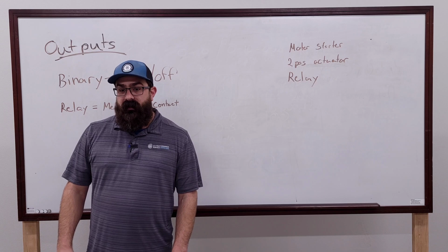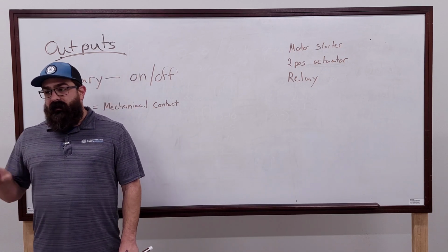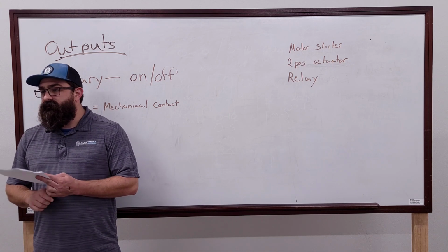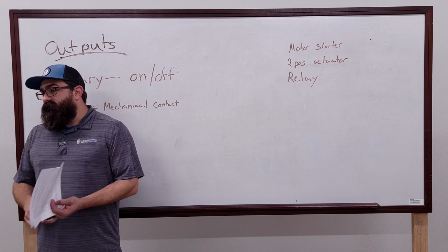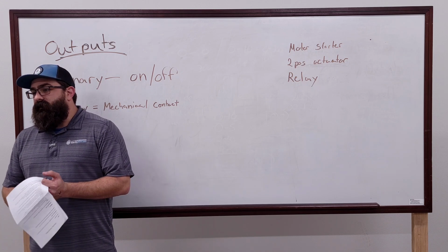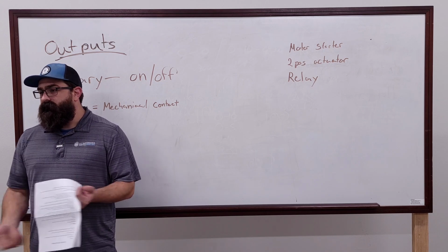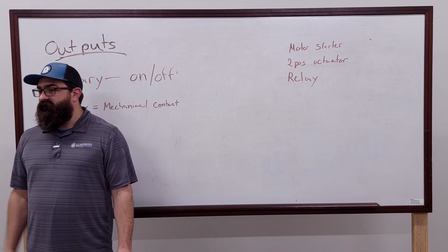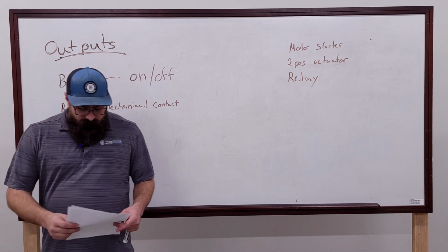Yeah, but they're DC only also. They can't do an AC voltage. This tech is the only one we deal with that has transistors, so that's why I wasn't going to go super far into it. And we don't usually use those to drive relays if we don't have to. We usually use them to drive valves and things like that. So then it doesn't matter.